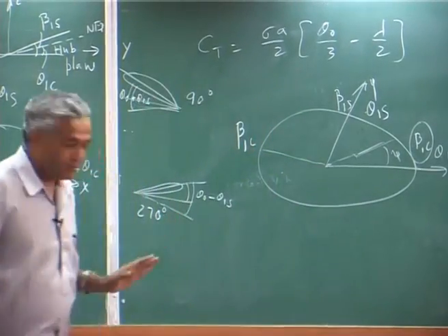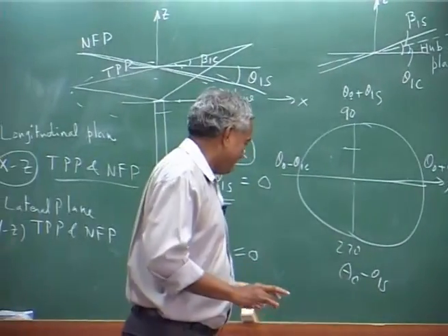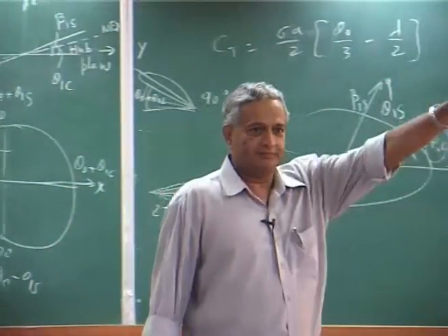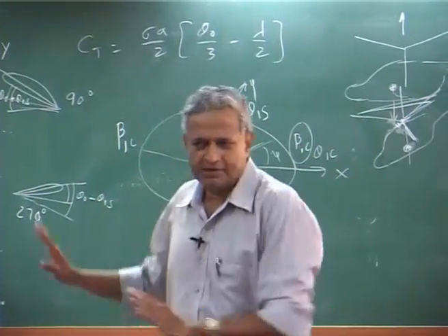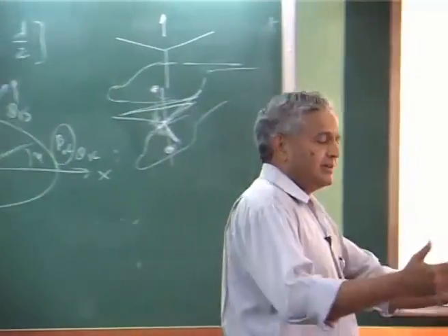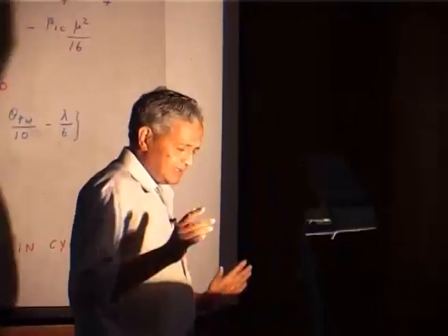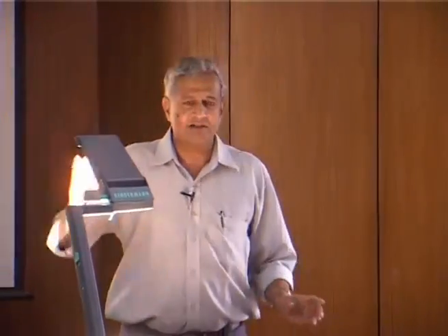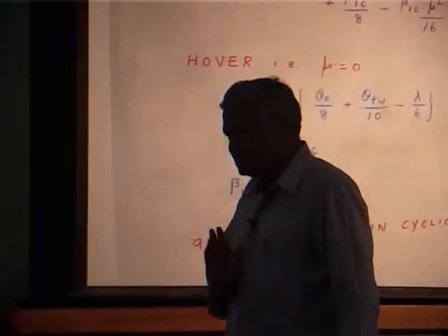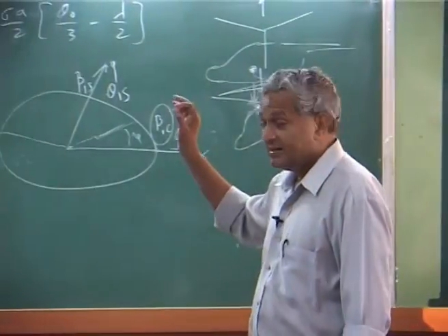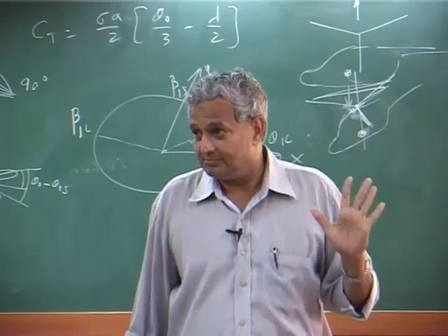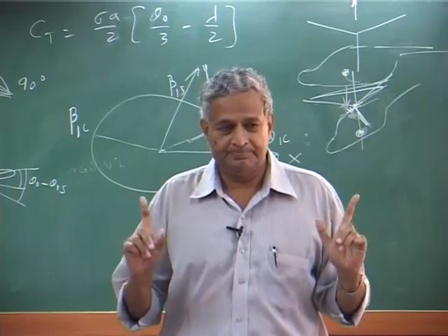Okay. Now, the relation between input and flap is clear for a very simplified case. Now, if you complicate the problem, because all this is, that is why industry will usually say the input has a 90 degree phase shift, but 90 degree is valid only for a centrally hinged blade with flap frequency 1 per rev, that is 1 omega.